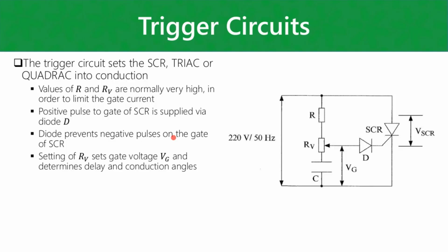Okay, so obviously you need to trigger an SCR at a specific point in time. Now, for some reason in this subject, we mainly look at very rudimentary trigger circuits. In reality, we don't actually use trigger circuits like this anymore because they're very inefficient in terms of power usage. And that is just a simple RC circuit. The thing that's left out in this drawing, though, is maybe a load. Otherwise, you're just going to have a dead short there with your SCR.